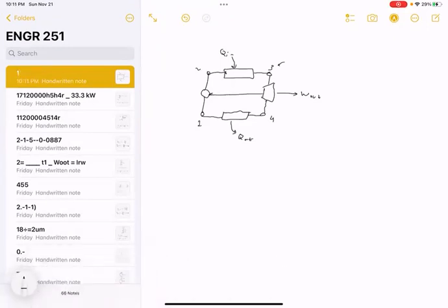Now, keep in mind, in most Rankine cycles, you can oftentimes neglect the work of the pump because the work of the pump is pretty small in comparison to the work in the turbine. But since they give us an actual specific value, we're going to go ahead and assume that it's important. And if later on we see that it was small, then it was small, and we can neglect it later on, or say that it's negligible.